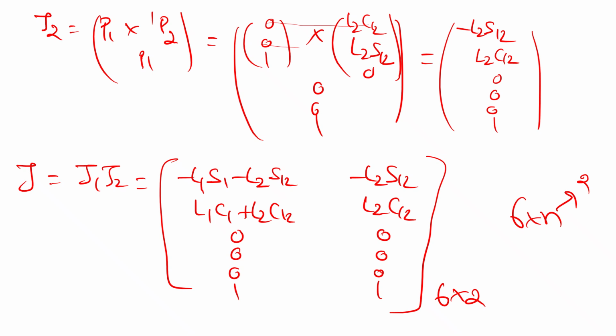In this we have seen what the manipulator Jacobian is. It relates end effector velocity with the joint velocity. The user is always interested in knowing the joint velocity, and for that we have to derive this. So the Jacobian for prismatic and rotary joints is given. The Jacobian comprises the top portion, which is linear velocity, and the bottom portion, which is angular velocity. It is the position vector only. You just have to take the position vector and do the cross multiplication, or take the position vector and arrange it, and that gives the Jacobian.